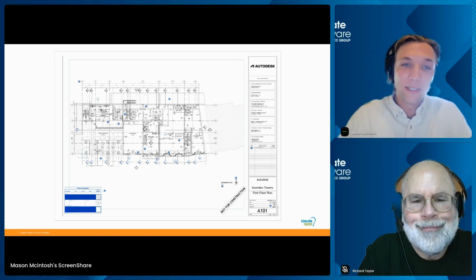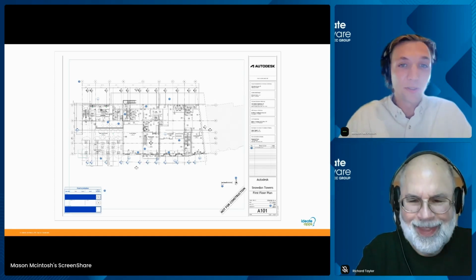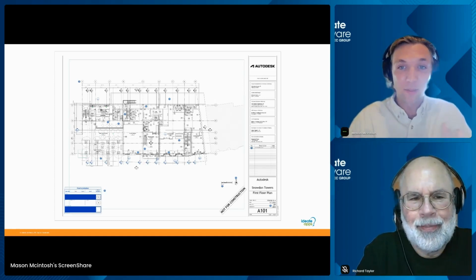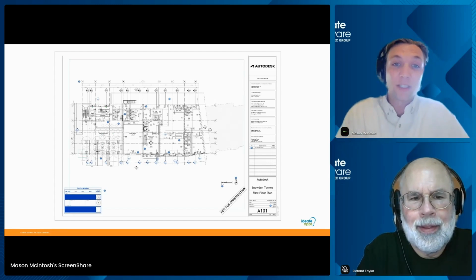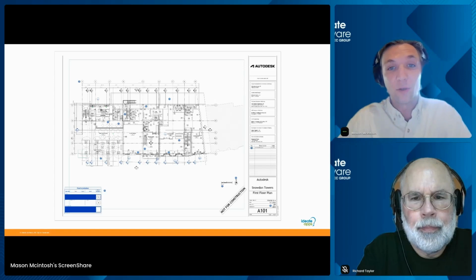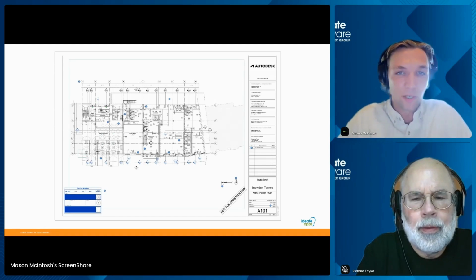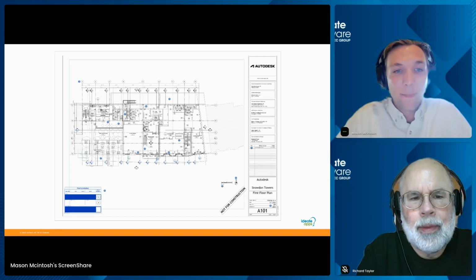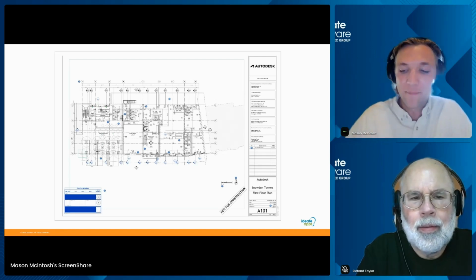Placing your notes, there could be multiple views within a sheet, schedules, and you're really just using this as a template to align all of your other floor plans. Because in certain projects, you'll have a dozen floor plans within every level that need to be in the exact same place, and you just want a really, really quick process in being able to align those. And then also your schedules, just actually getting them so that they don't move every time.